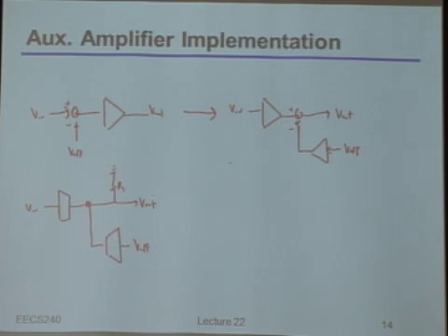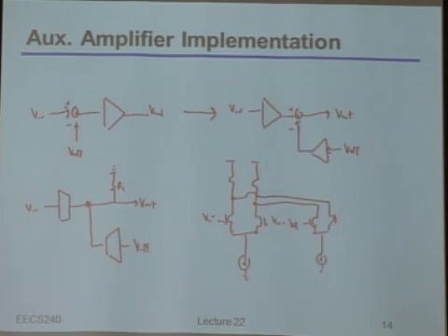Okay, so just to be absolutely 100% clear, if I was to do this with a simple resistively loaded amplifier, that would imply the whole thing would look something like this. So I'd have my V in plus, my V in minus, then I'd have a second differential pair that would then be connected to something like V off plus and V off minus.